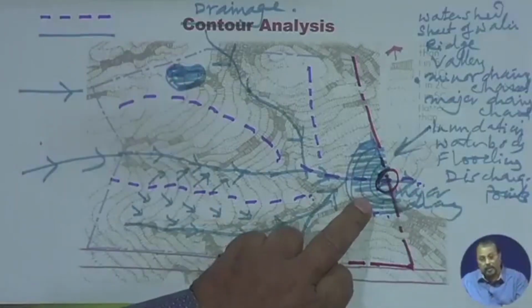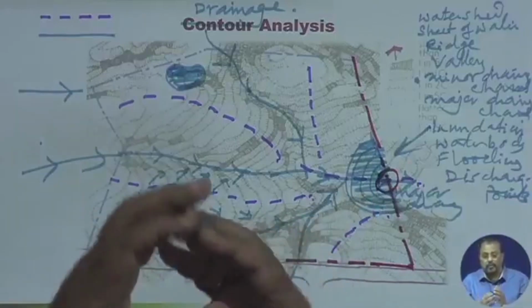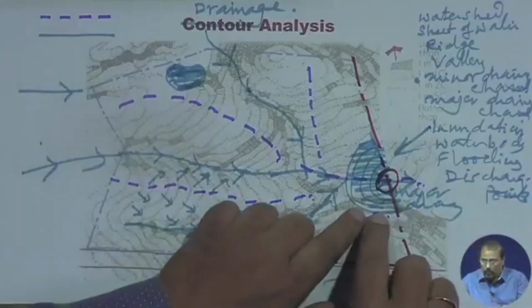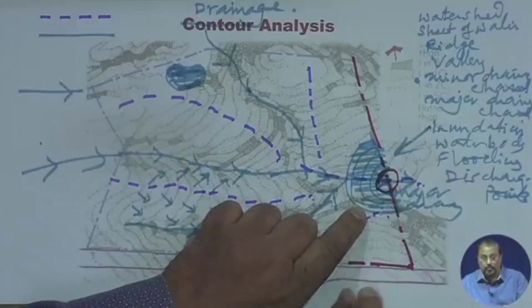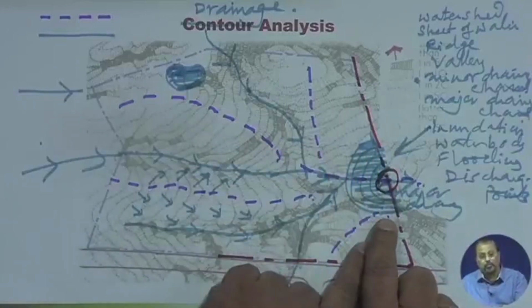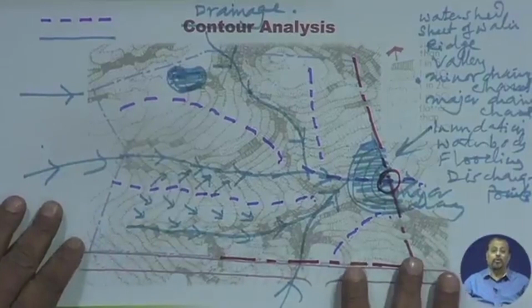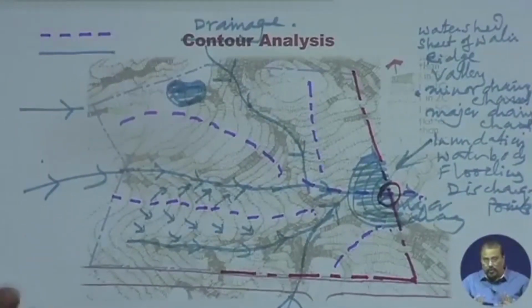Inundation area is such where you will find that the water is going to go out in some time. Okay. If the inundation area is not cleared in quick succession, then this area will be subjected to flooding. So when I'm going to do the drainage analysis of this, I'm going to check all these aspects. I hope this point is clear.